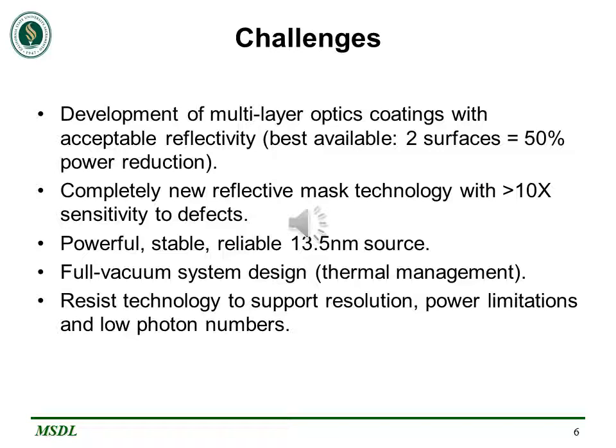There are a number of challenges going forward with EUV lithography. The first is to develop multilayer optics coating with an acceptable reflectivity. The next would be to develop a new reflective mask technology which is 10 times more sensitive to defects.